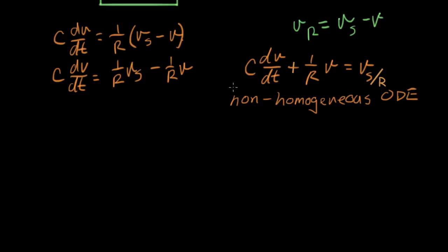This equation is a little tricky to solve because this is not 0 over here. We have a mixture of things going on here. This side of the equation represents the forcing function. This is what the circuit is being driven to by that step response input voltage source. And this side here is going to get tied up with the initial conditions that the capacitor has. So there are two things going on here that make this a little more complicated than usual to solve.